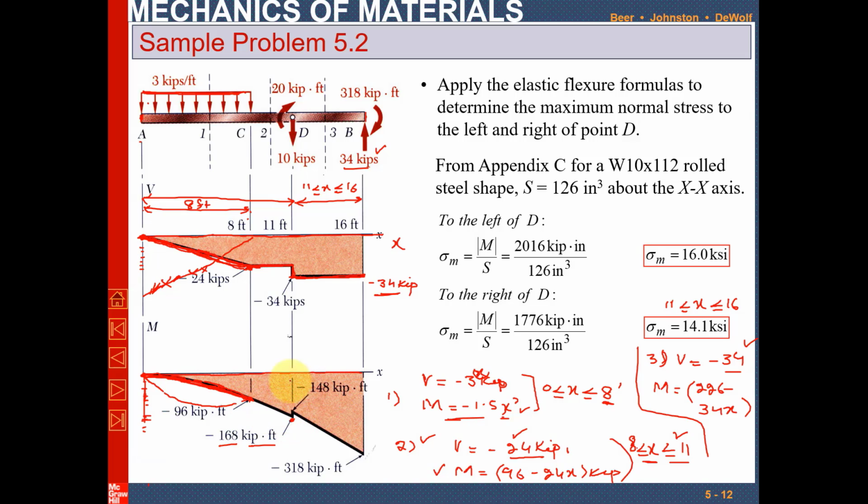Now how to join? You will look at the shear force diagram. Now you can see the shear force diagram is a constant number, or a line with zero slope. So definitely the bending moment line will be one degree higher, so it will be a linear line.